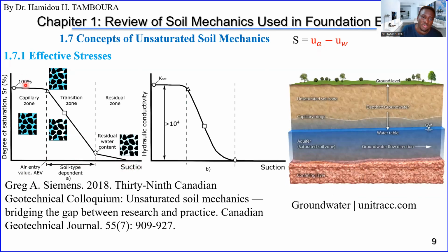So we can see here the degree of saturation. When the soil is saturated, maybe the suction is 0. And when the saturation is decreasing, the suction is starting to increase. From here, when the significant decrease of saturation is starting, we call it the air entry value,